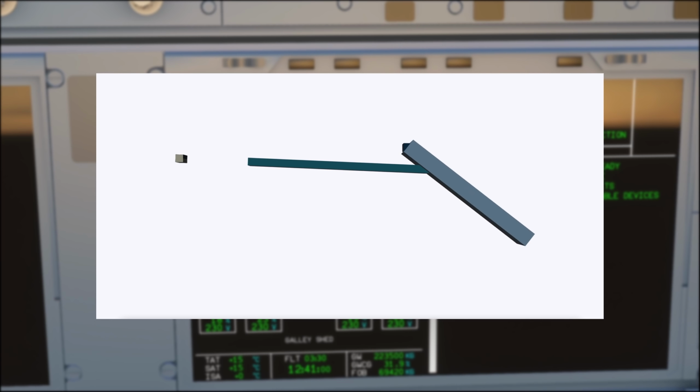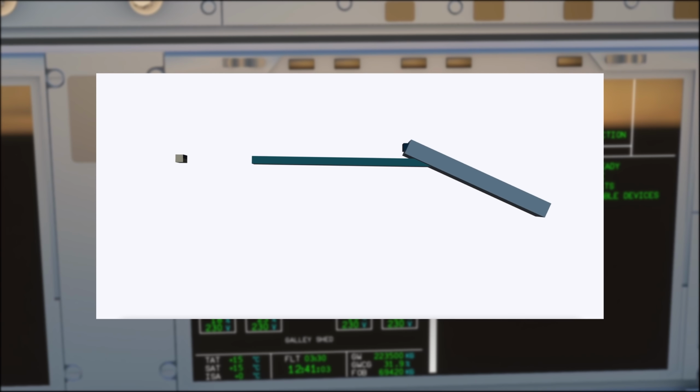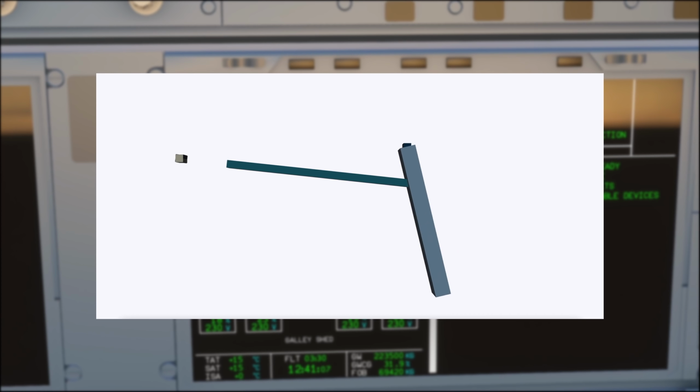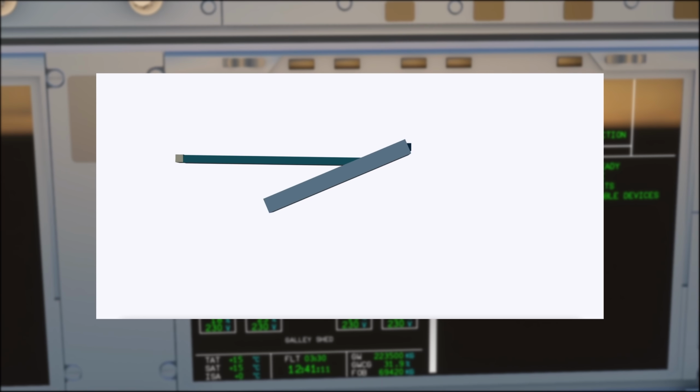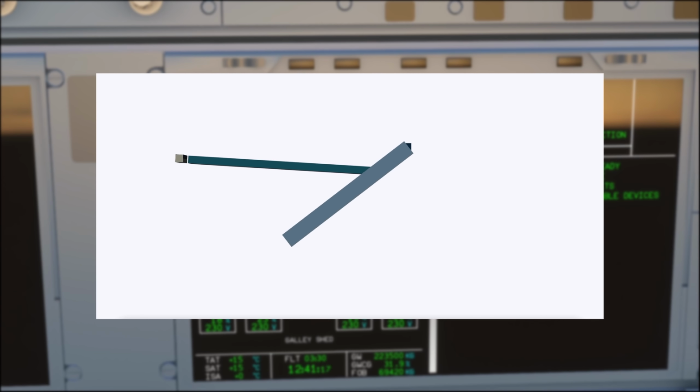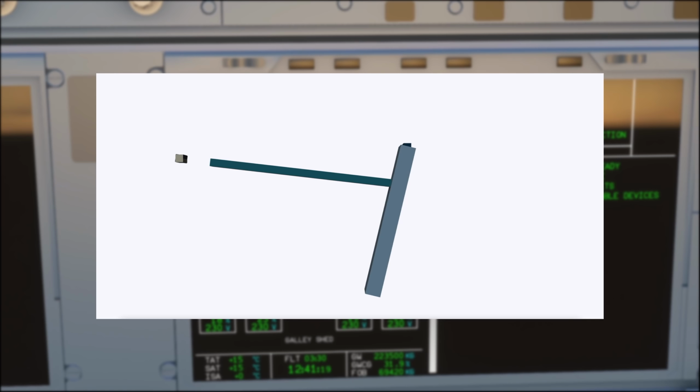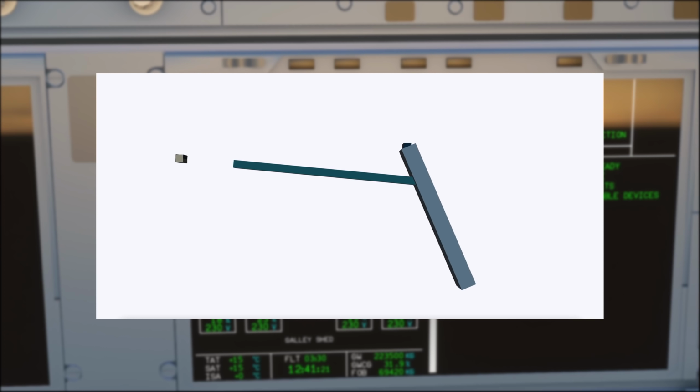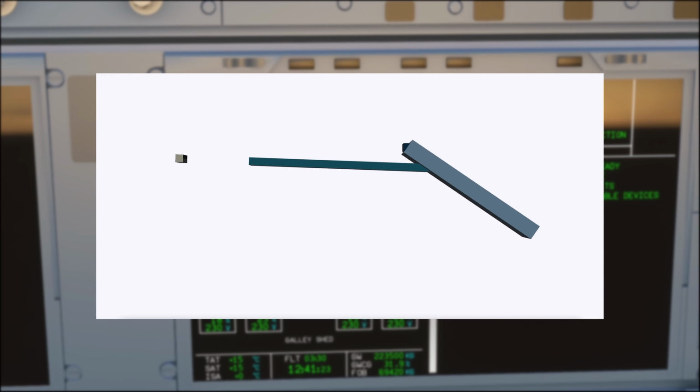To illustrate this system at work, here's a debug rendering of a hydraulic actuator, which are used to extend things like cargo doors and landing gear. There are no special animation formulas, custom tweaked low-pass filters to emulate this movement. We purely use a physics engine and apply the forces from compression of the fluid in the actuator's two chambers. This gives highly realistic behavior, such as the wobbling, automatically.